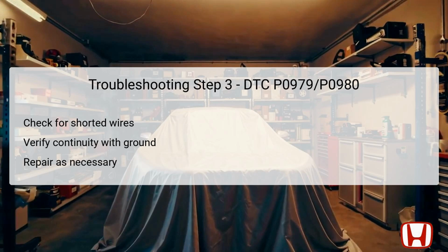However, if tests confirm there are no shorts, you can deduce that the wiring is intact. And the recommended next step would be to replace the hydraulic control unit itself, as it may be defective.